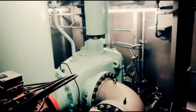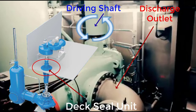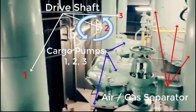So there you go. Right, I'm just gonna show you a quick close-up, and I will pause in this area. Right, we are looking at the right side of the pumps, viewing towards the stern or engine bulkhead, and this is the discharge outlet of the pumps. Driving shaft coming down from the deck seal unit, air or gas separator, and lastly, this is the cargo pump, single stage, radial type flow, can be fitted with steam turbine or electrical motor drive system. And this is the full view of all the cargo pumps, 1, 2, and 3 shown in here.